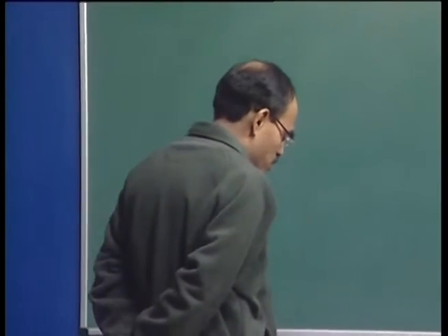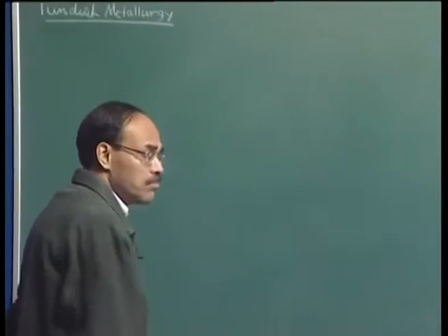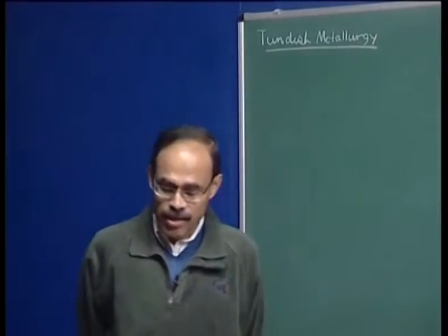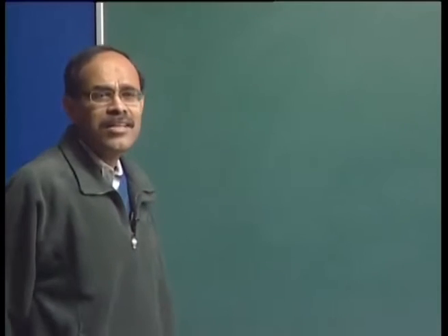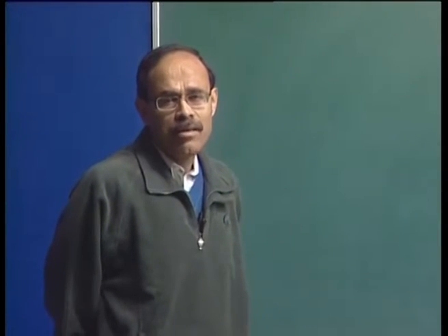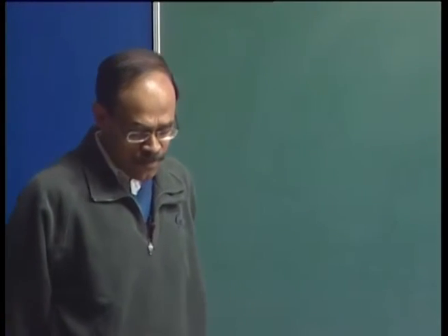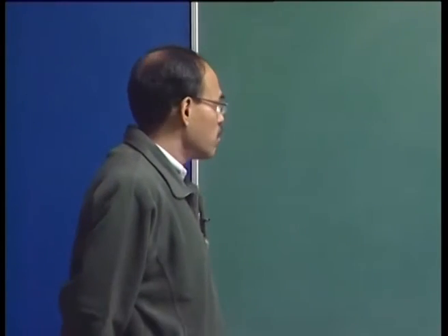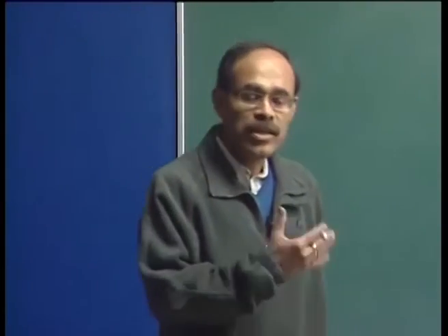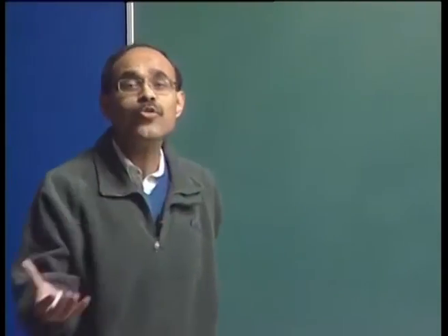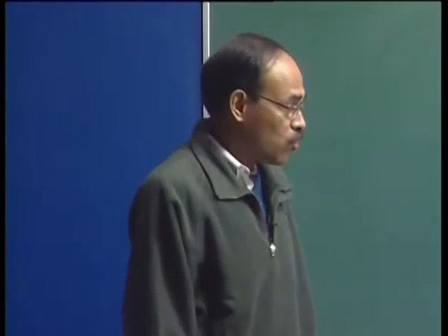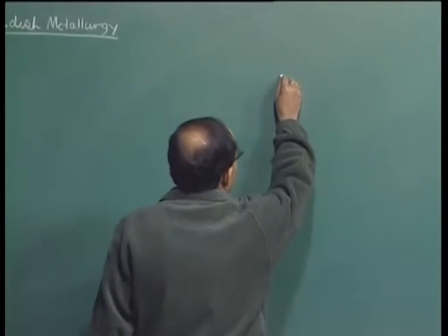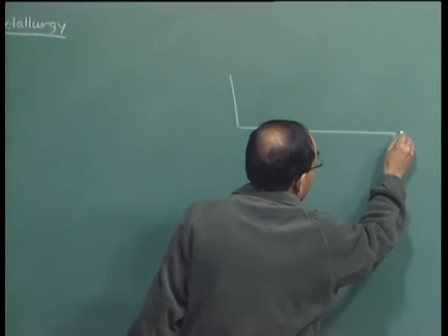Okay, when I was a student some 35 years back, we had nothing on tundish metallurgy. Actually, tundish metallurgy was not developed then, although continuous casting has made inroads in the area of steel making. But today, tundish has, as I have mentioned already, occupied a preeminent position in the steel making circuitry. And this is because of the simple fact that in tundish we can overwhelmingly control the characteristics of steel in terms of its inclusion, in terms of its composition and temperature, and thereby produce the right kind of cast products through continuous casting.